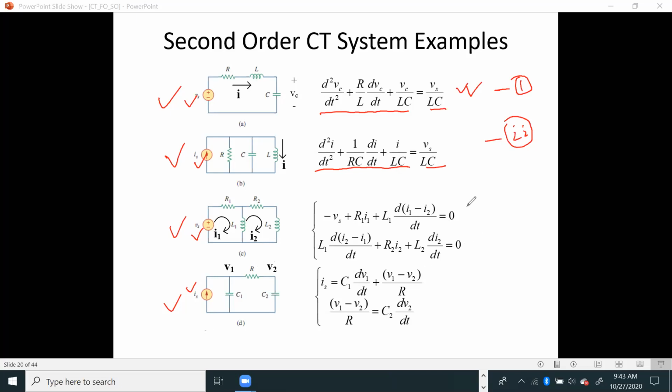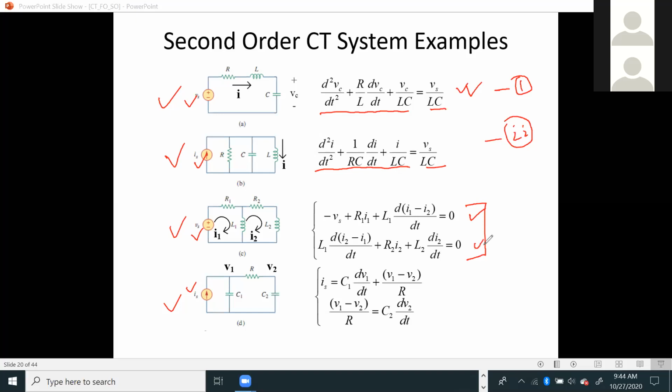So you can easily find the loop analysis. This is not a resistive circuit. As transient or rate of change will be available, voltage or current related to a capacitor or inductor should be written in differential equation form. So your first equation is the loop equation for loop 1, isn't it? Yes, sir. And your second equation is the loop equation for loop 2. These two are differential equations, aren't they? Yes, sir. Can you merge them to form one?